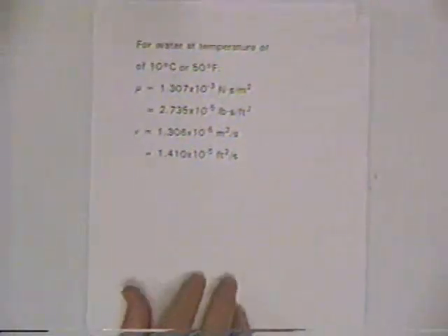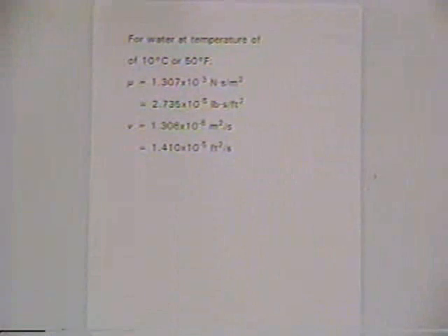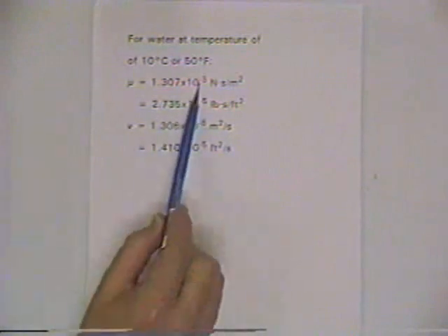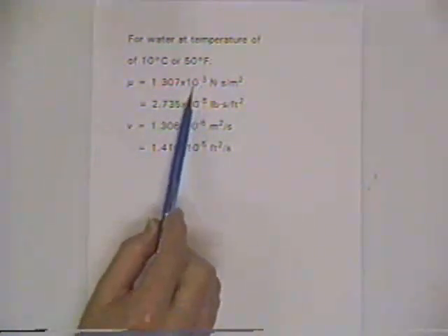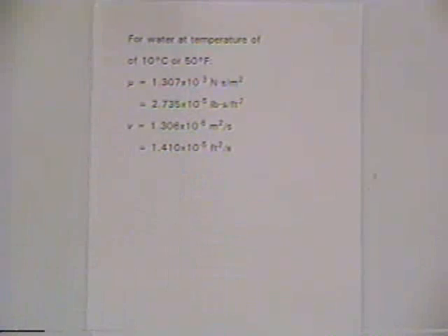And again, there are tables that provide viscosities as a function of temperature, and some typical viscosities are given here for some typical temperatures. And you always remember that viscosities are very small numbers, because it's easy to leave the minus signs out. They're 10 raised to the negative 3 or negative 4 or negative 5 or negative something power. Small numbers rather than large numbers.